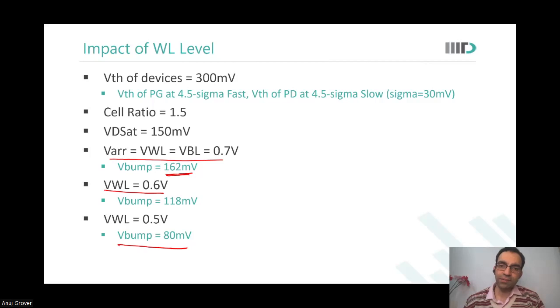You're able to see this? So one thing I need to ask is that while reading, we are looking at two kinds of things. One is the cell current and one is stability. So when I say the read assist thing, I would be basically targeting the stability thing, the Vx. Not necessarily, Raghav. You may use two assist schemes in parallel. One assist scheme recovers stability, the other recovers cell current. If you go on my Google Scholar page, you will see one of my papers where we actually use multiple read assist schemes in parallel to do exactly this.